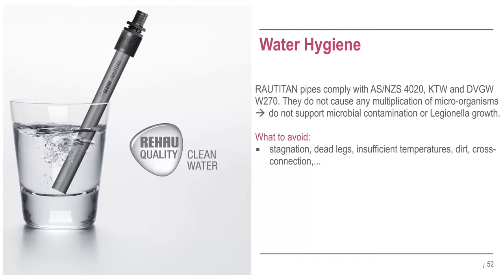Rehau takes water hygiene very seriously. The Rautitan pipes are compliant to AS/NZS 4020, KTW and DVGW W270. The Rautitan pipes do not support microbial contamination or Legionella growth. Still, it is good practice to avoid stagnation, dead legs, insufficient temperatures, dirt or cross-contamination.